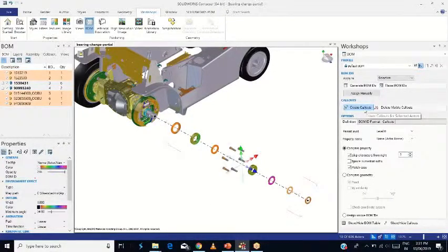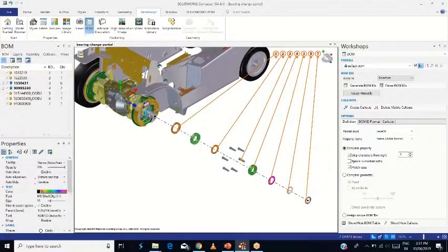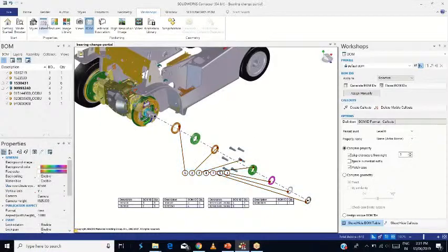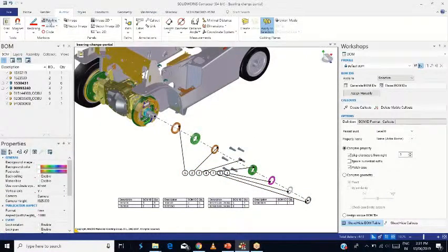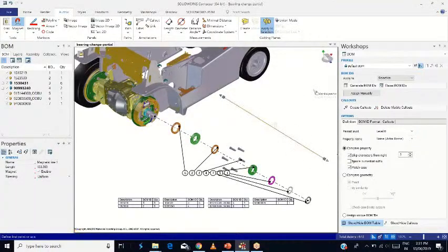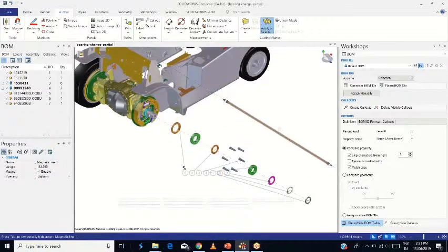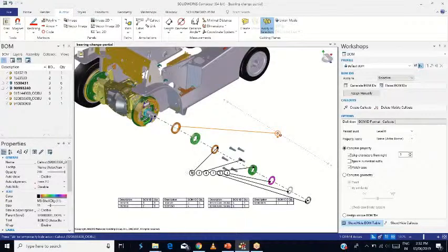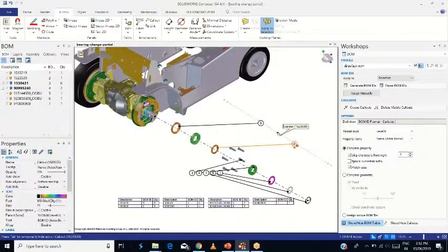And also if I want to create these callouts, again it's the same, just create callouts for the same, it automatically creates those callouts for you. Now I'll just show the bill of material table. If I want to arrange this, I have many options, like this magnetic line in this case. So I'll just draw a magnetic line, and I'll just keep these callouts at that place. So it automatically magnets to the line, and it automatically aligns as well.